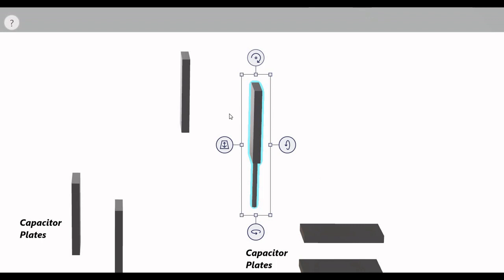So once we have measured the liquid column pressure and the level of the liquid, we can calculate the density using the formula density rho is equal to PL by gh, because acceleration due to gravity, 9.8 meter per second square, is constant. So this is all about density measurement using bellows and capacitive transducer.